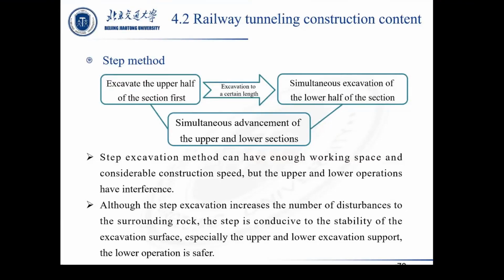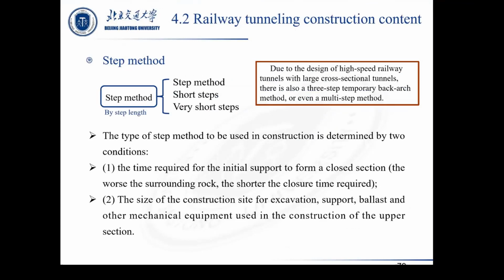And the step method can be divided into long step, short step, and ultra-short step according to the length of step. Due to the design of high-speed railway tunnel with large cross-section, there are also three-step temporary method and even multi-step method.